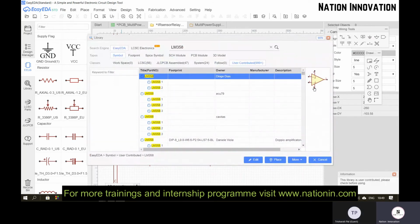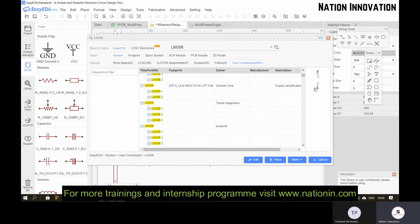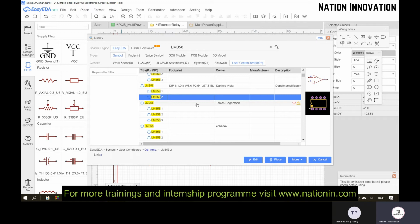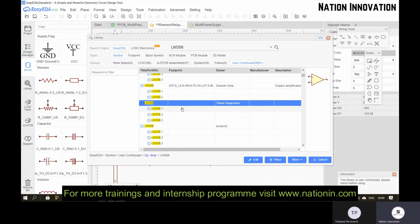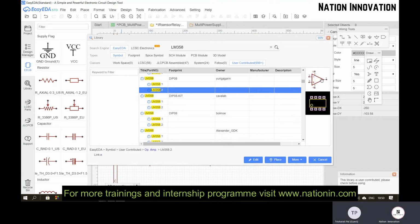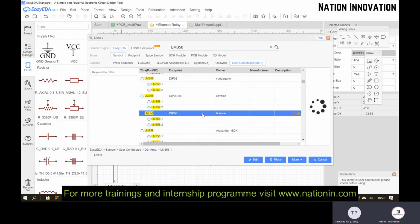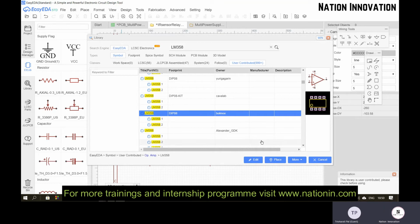And this is how it looks. Just search for one component which has both the footprint and the symbol. It has a footprint, but it does not have all the pins. So let us search for a better component. You can select this one. It shows all the pins here, and it has all the component pins also. I will select this.